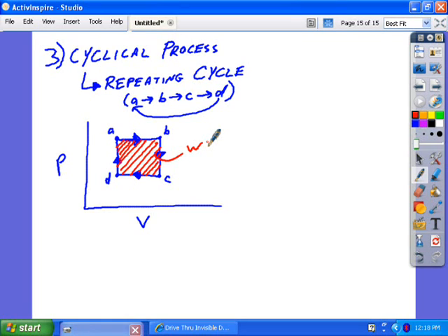Now, if you were to look at this exact situation, in order to start at a lower volume and go to a higher volume, we're staying at the same volume here, I apologize. You go at the same exact volume, but you go from a low pressure to a high pressure. The only way to do that is to add heat. When you go from a low volume to a high volume at a constant pressure, that means you have to add heat.